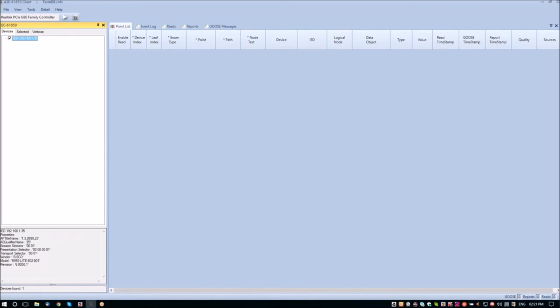The connectivity parameters of the IED will be listed down. These are some of the 61850 and MMS parameters, which includes some OSI addressing as well. Further, the second tab in the same pane can be selected. Once the tab is selected, the 61850 client will try to discover that IED configuration from the network. It will connect to the IED, and using 61850 operations, it will fetch the configuration and data models of the IED.